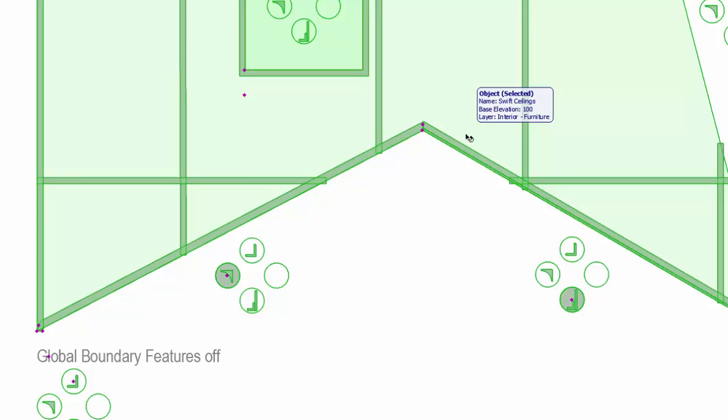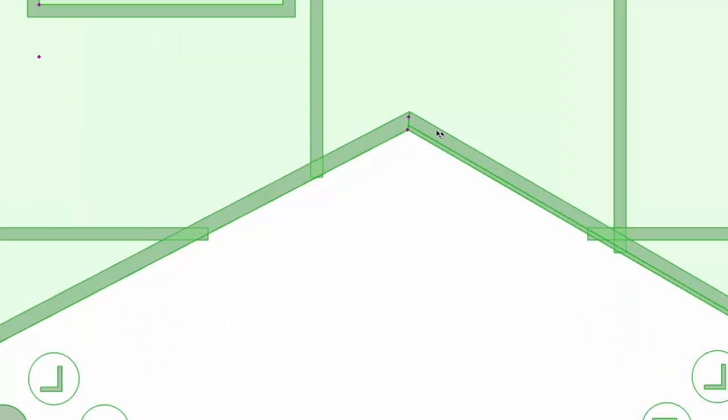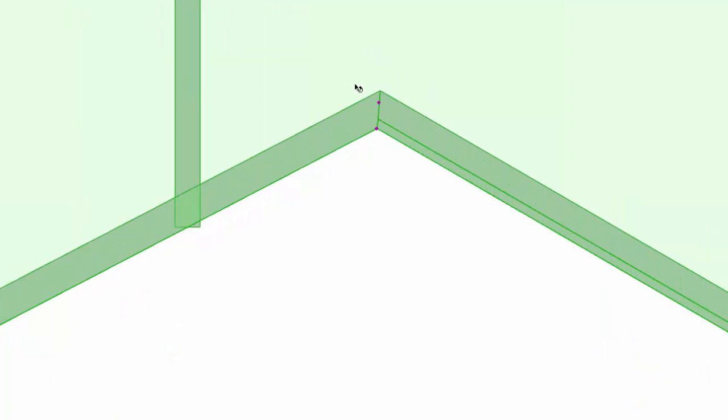What I would have to do is put in a whole series of conditional statements saying, you know, what quadrant the first line starts in and what quadrant the second one's in, and based on that it nominates which angle. Put simply, there's a lot of maths that needs to go in to actually work out exactly what that angle is and therefore determine the bisector and get these things to meet perfectly. The other reason is that a bisector of the angle, whether it be the obtuse or the acute angle, is not necessarily going to be perfect because the 2 components may be of a different size and therefore you don't want the exact bisector.